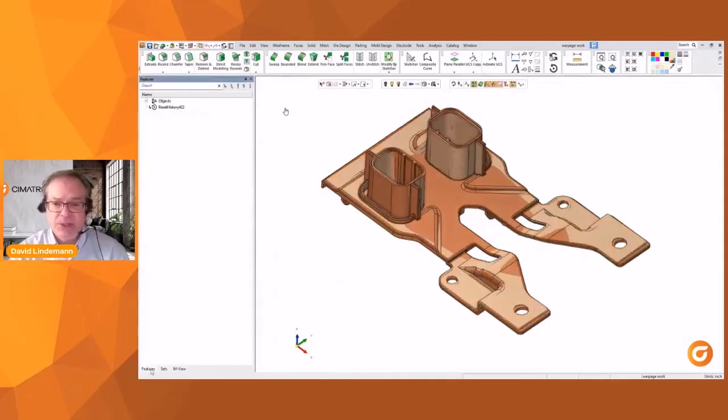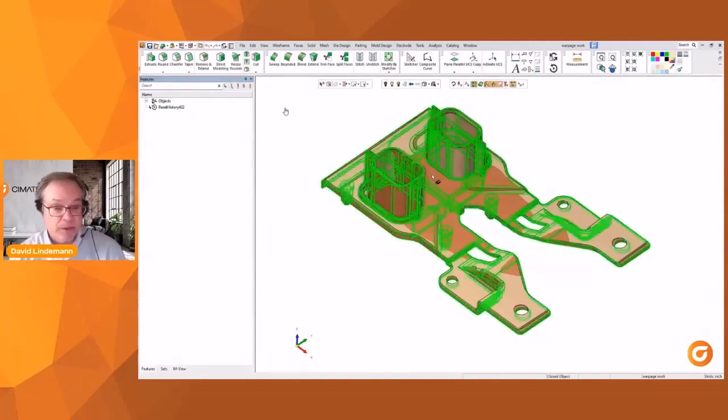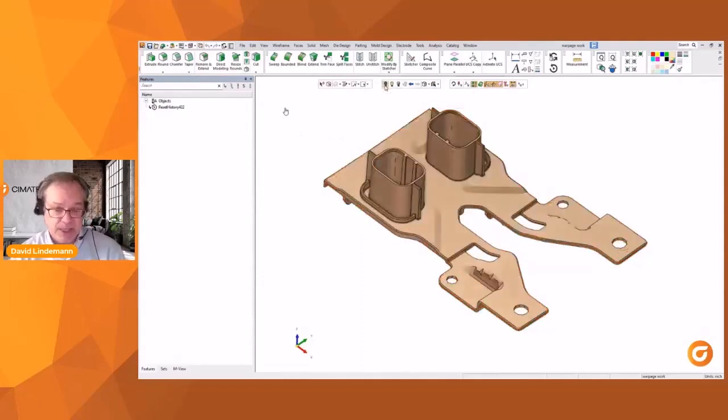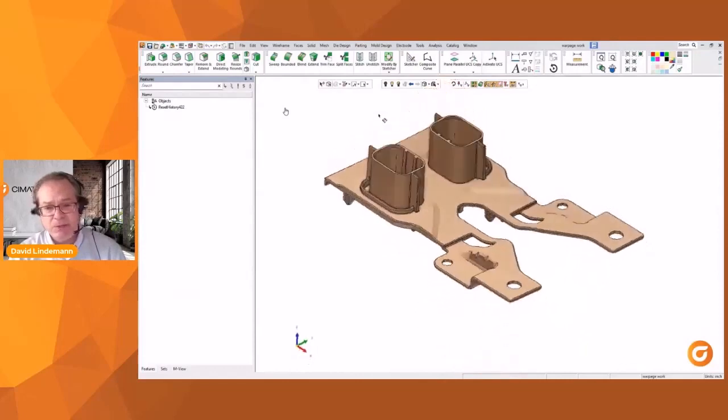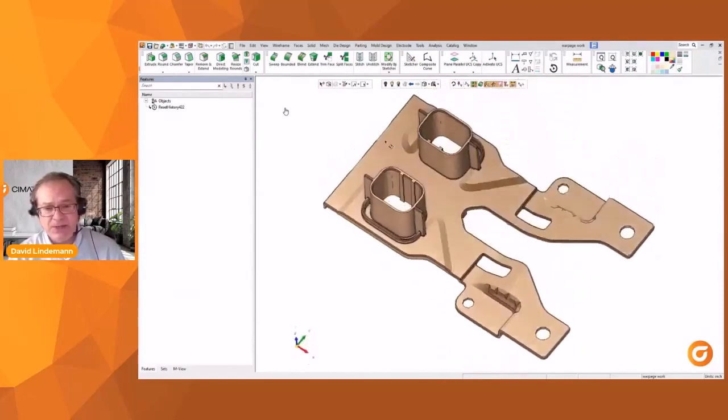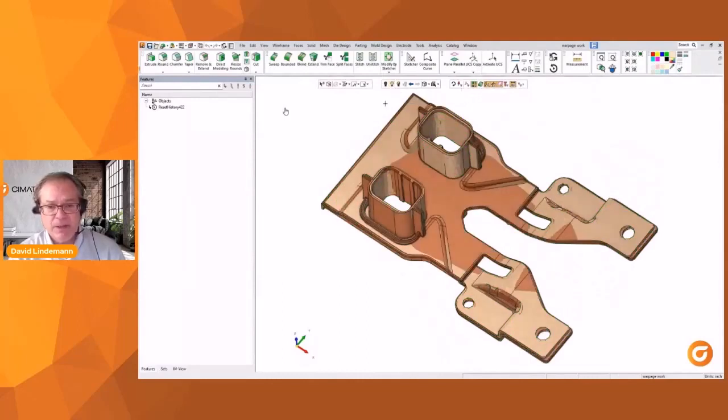So again, here, let's look at the two, and I can see they don't quite line up even. I know that one is smaller. The STL will be smaller because the simulation has accounted for the shrinkage. So from here, I want to work with the two and get them on the same plane, same location as what we're working with.